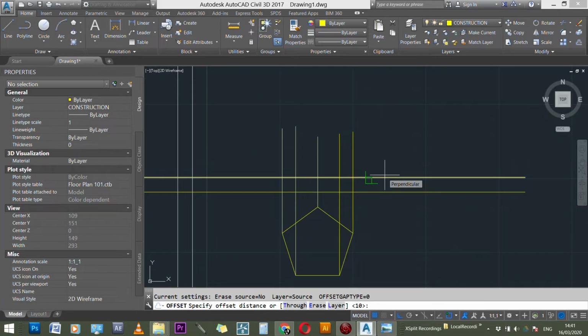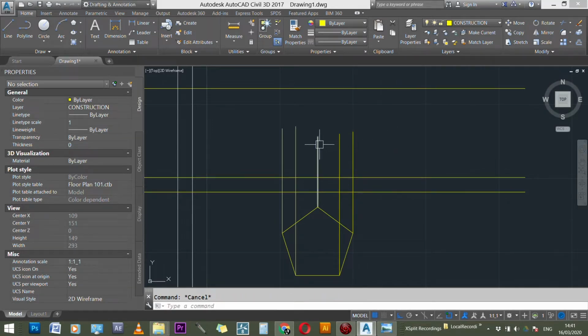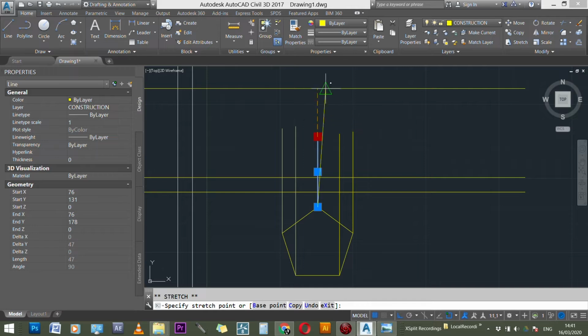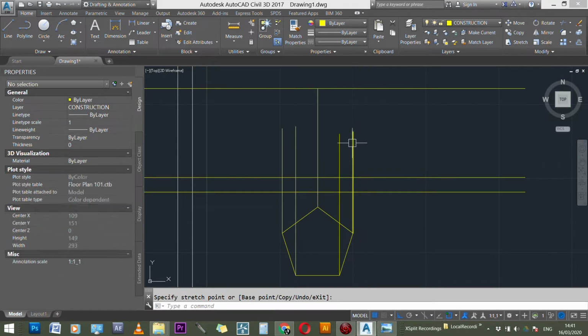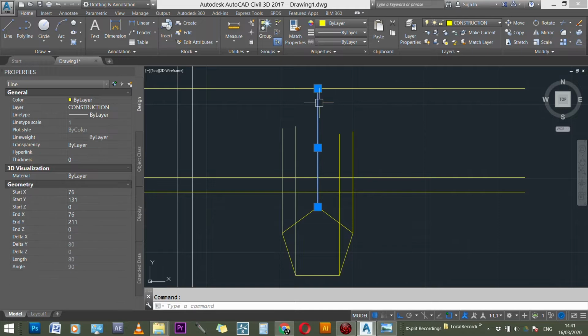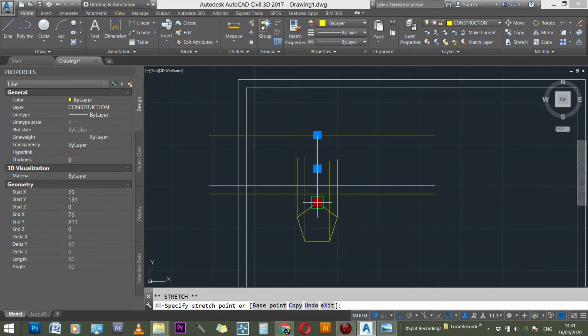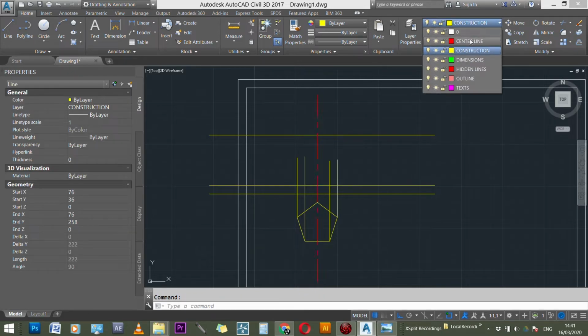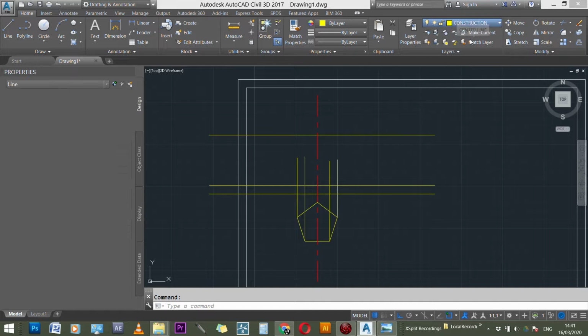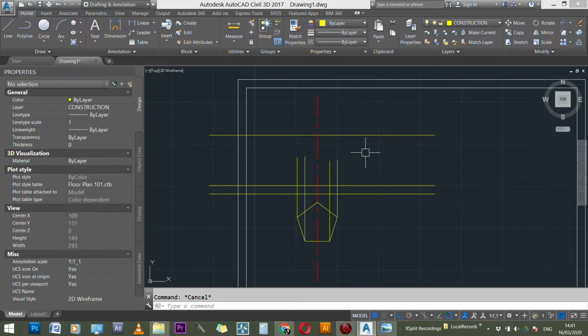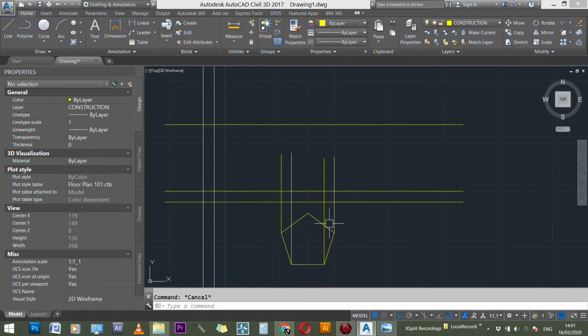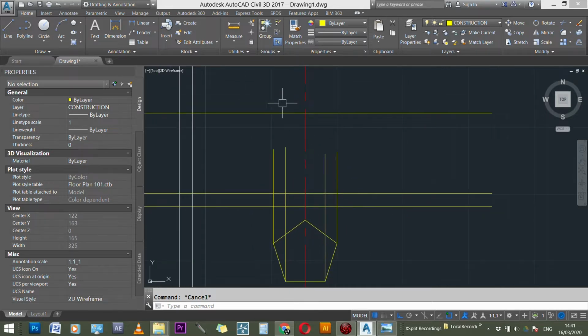First, offset 60 millimeters. Hit O for offset, type in 60, enter, and I've gone up there. I'm going to use this line, project it up to that point. I'm actually going to change this line here to something called center line so that we can identify the center. So I'm going to come over on my center there, and I have everything set up. That is my center line, so I know that's where my center is.